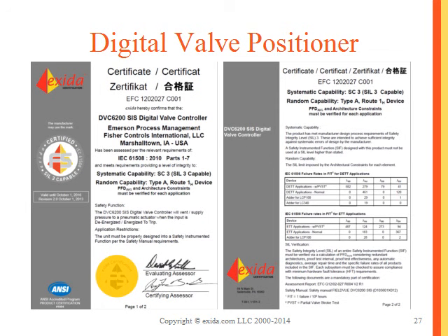Then we have a digital valve positioner here, and again, I randomly picked something, and this certificate actually matches what I was just showing you. It has the ANSI logo here, including the 1004 identifier for the exida accreditation scheme. It shows the valid until and the revision date, the mark that the manufacturer can use. Again, 61508, SIL 3 capable.